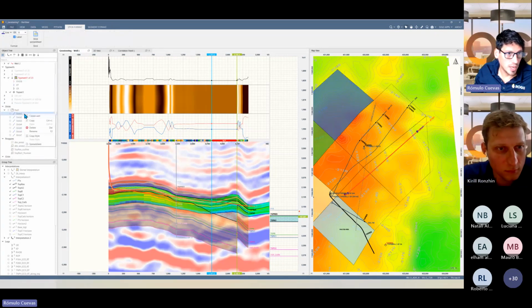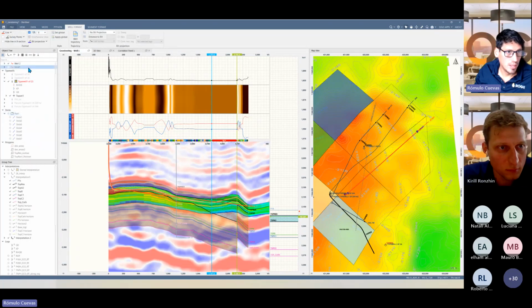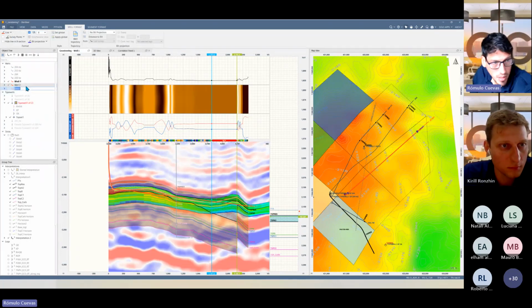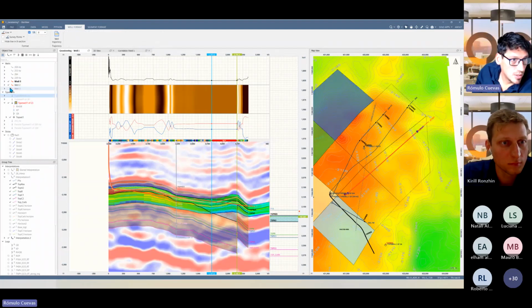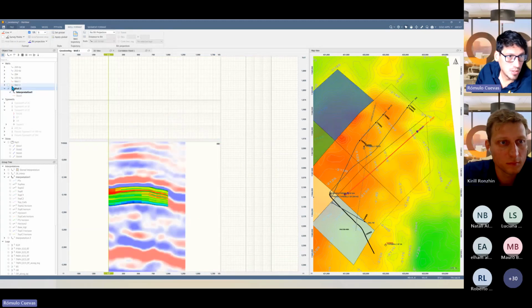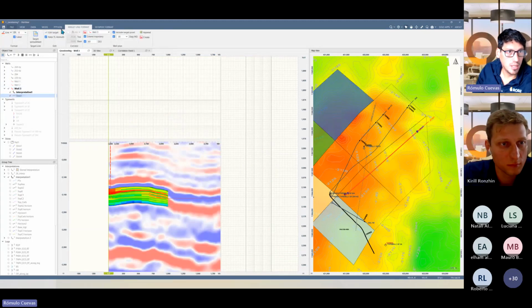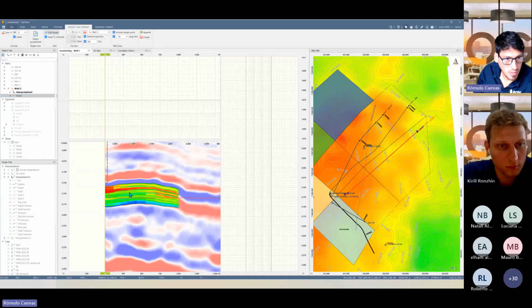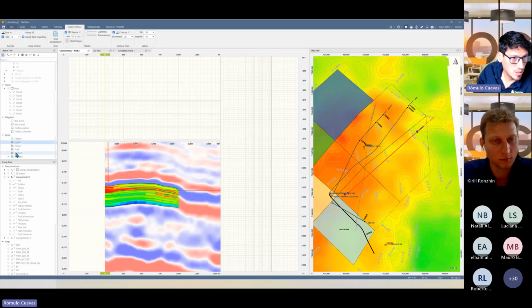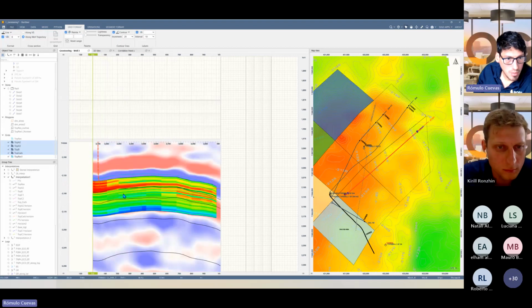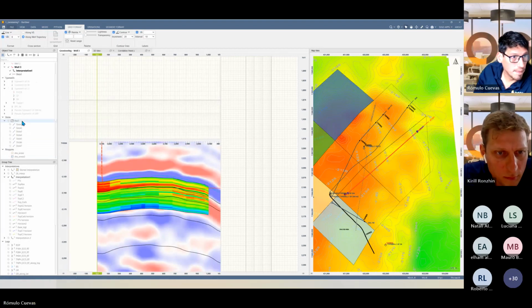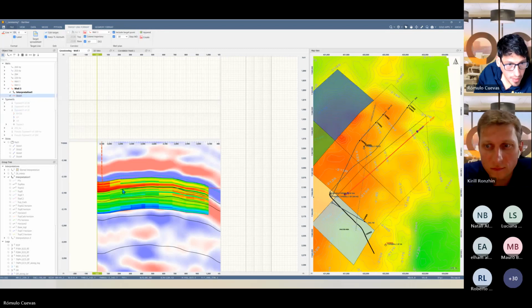So again, I right-click in the stick, creating a well. So let's put well plan number three. Same process. I treat this like a target line. Okay, like this. I take it and put it inside of the reservoir over here. Let me turn on the grids. Okay, I put it there.